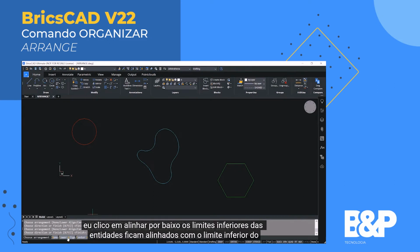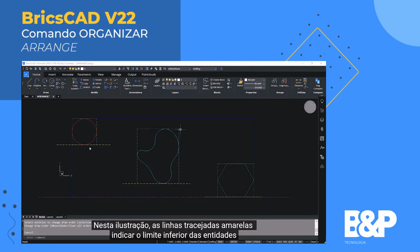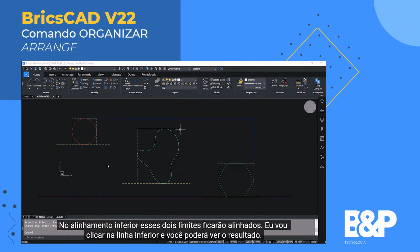When I click on lower align, the lower bounds of the entities get aligned with the lower bound of the selection set. The lower bound is determined by the smallest coordinate in the y-axis direction. In this illustration, the yellow dashed lines indicate the lower bound of the entities and the magenta dashed line indicates the lower bound of the selection set in the y direction. In lower align, these two bounds will get aligned.